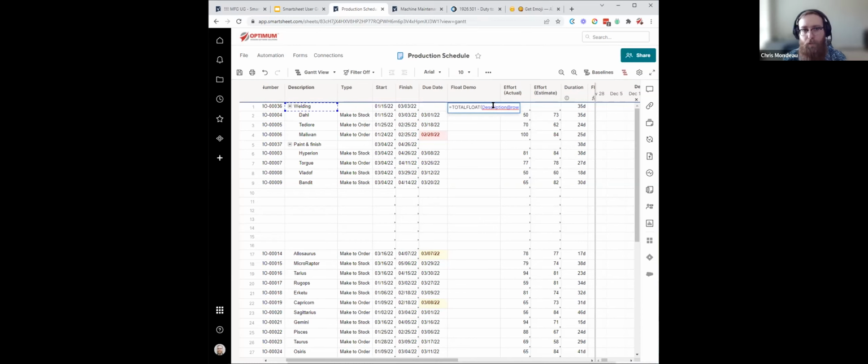It doesn't have to be called description, but if I enter this, and then if I right click that cell and convert to a column formula, it'll fill it down and make it stable, and that'll give me my total float. So the float will change if there's dependencies from task to task and go from there. So